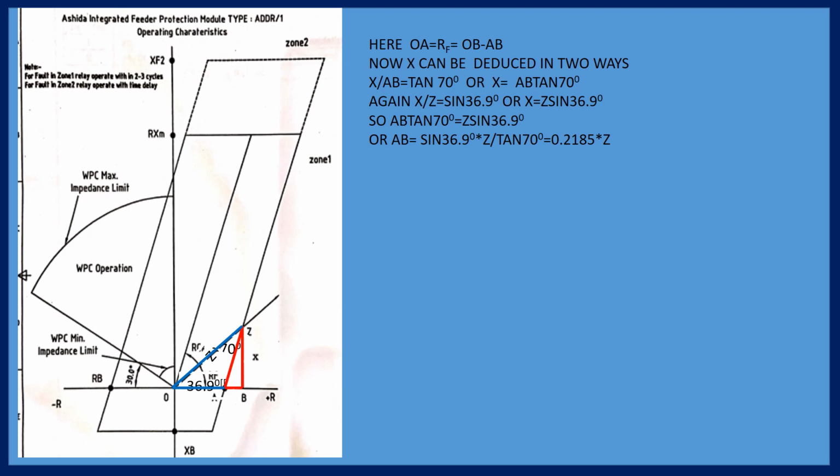Then your lightning arrestor. The lightning arrestor is connected with one end to the phase and the other through the bond to the earth. Earth is the earthing mesh, and a separate earth electrode is also used. For each lightning arrestor, you have to use a separate earth electrode, earth cone. Don't forget it, okay? Each lightning arrestor needs a separate earth cone. That is the lightning arrestor.